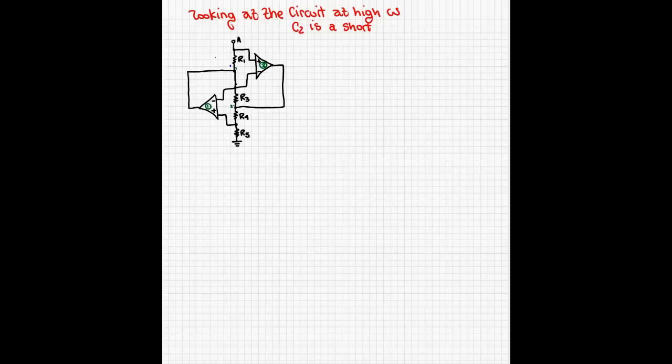So where is the current that's coming from R3? Well, it's going into the low impedance pad of op-amp 1 right here through this wire right here. And then op-amp 1 is going to try to make its negative terminal equal to its positive terminal. And then once it does that, you're going to end up with VA, Vin equal to the negative terminal op-amp 2, which is equal to the negative terminal op-amp 1, which is mirrored into the positive terminal of op-amp 1. So therefore you end up with VA down here through R5.